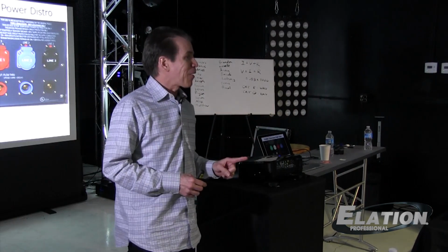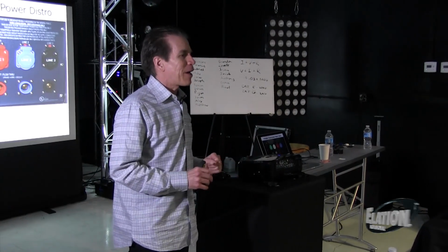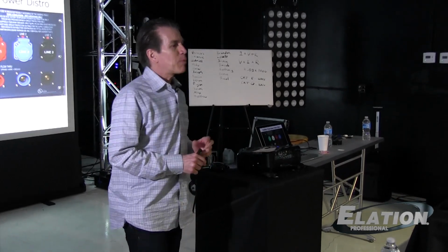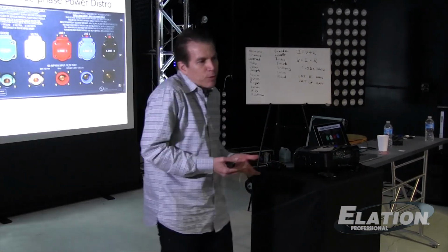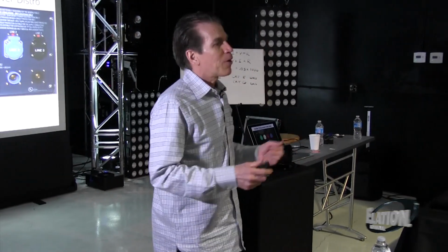But you do need a ground. You always need that green ground. That's a mistake that some people make. They say, well, I have a neutral, so I don't need a ground. Wrong, you do need a ground. That's really important, as we saw earlier.